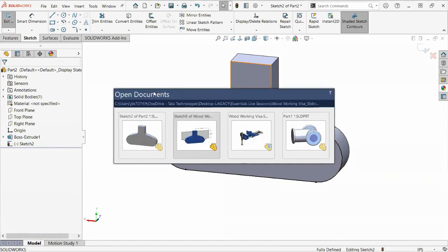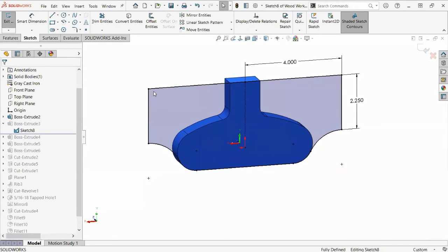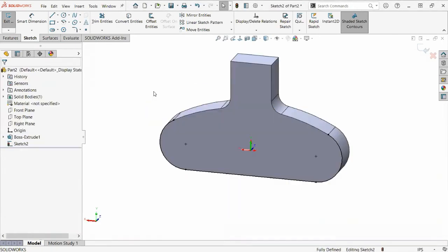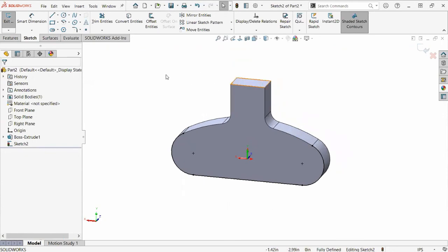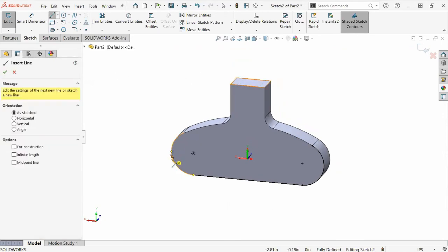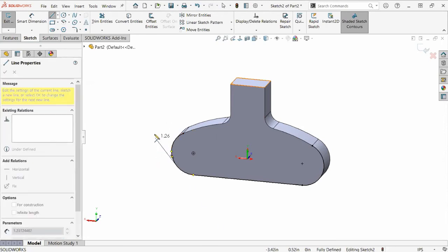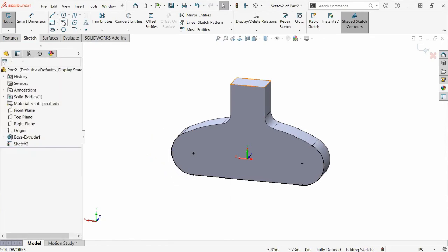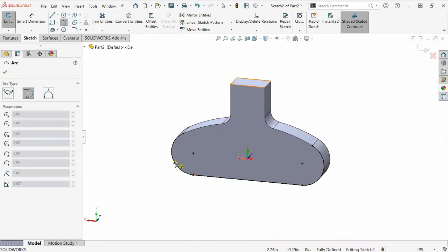I'm going to go back in and see where the sketch differs. Okay, go ahead and finish that. I could use mirror here, but I think I'm just going to go ahead and sketch a little bit more quickly. And I'm going to come off the edge of this existing one to create, I'm going to use an arc tool actually. So we've got center point arc here. What I want to do is create a tangent arc. So I'll start on that edge or on that existing line. Doesn't like that. Only wants me to be on the end sketch point there.